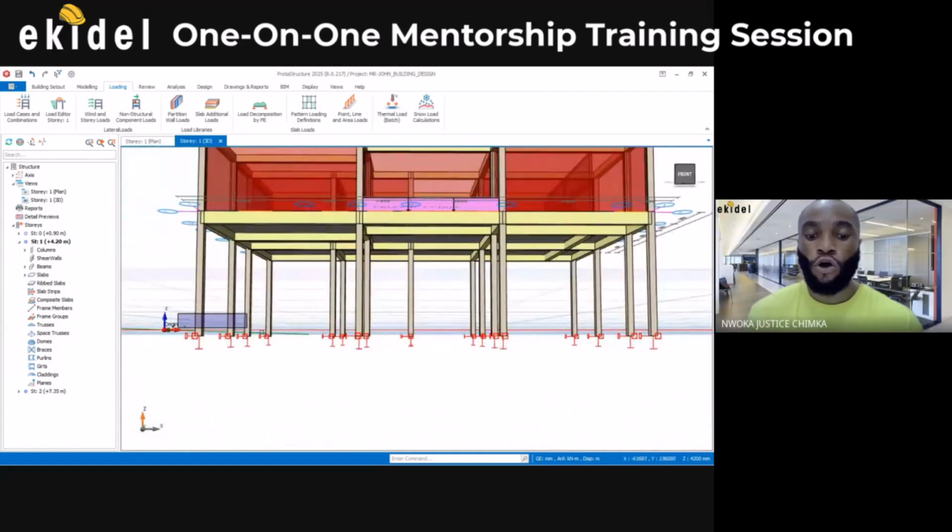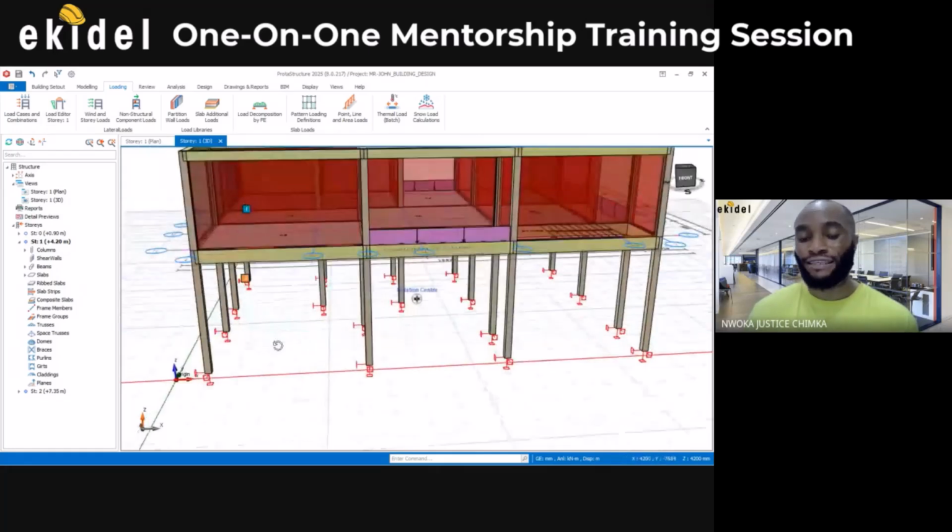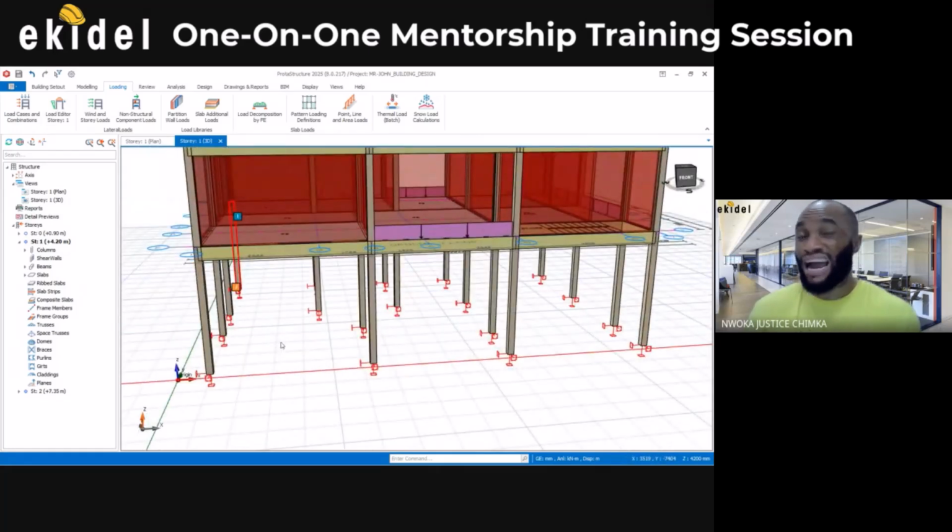Yes. Ground slab, although most people tend to add it. For me, most times I choose to add it or not, except if the soil of that place is very weak. If the block load is resting on the soil, and the soil is weak, there will be some kind of settlement, uneven settlement, which will make the block crack. So with that, I can choose to add a plinth beam that will carry the block.